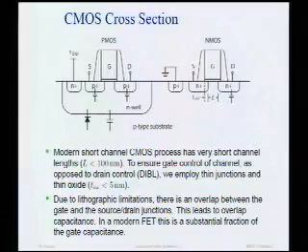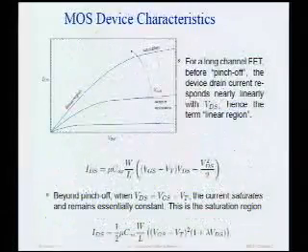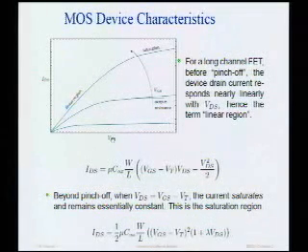If we look at the characteristic curve of a FET, in saturation region it should be flat. In other words, as I vary the drain voltage, the current should remain constant. Now, we all know that in reality the current will vary a little bit. We call that the output impedance of the device, the output conductance of the device, output resistance if you like.